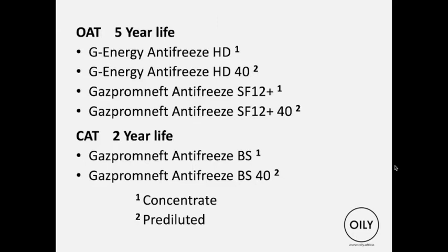And Freightliner in South Africa had a huge problem with mixed fleets of trucks. All Freightliners, but mixed engines, where they were losing radiators, getting pinholes in the radiators because they were using mixtures of antifreezes. They would get the Caterpillar engine with Caterpillar antifreeze and then start topping up with Cummins antifreeze, and it wrecked the radiators.